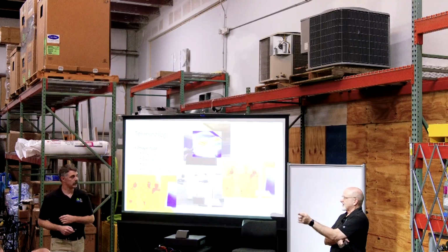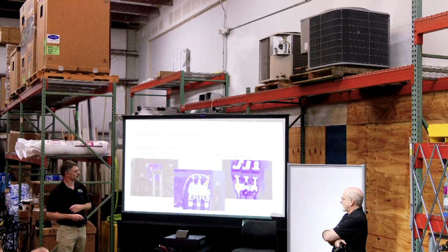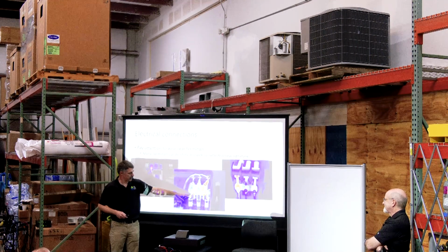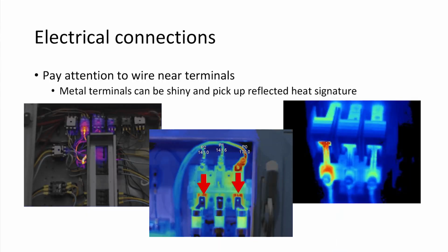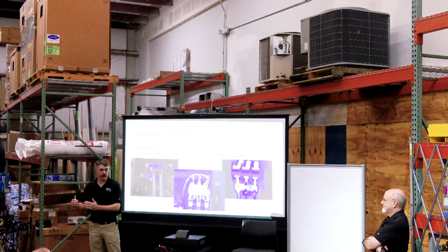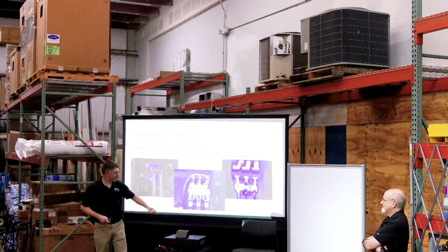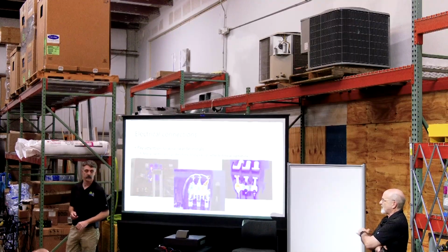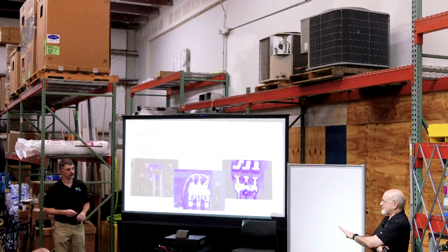So he asked, besides the connection, what else can cause that on the connector? So loose connection up here, these down here, if those are truly hot spots, and how I would find that is I would move side to side a little bit with my camera to see if I'm blocking something. I see how that image changes. That may be pitted or burned contacts on your contactor. So he's creating a thermal shadow so he can inspect the equipment.